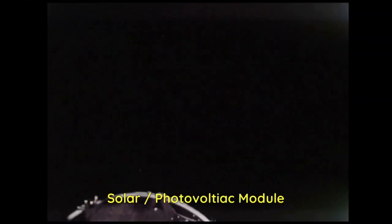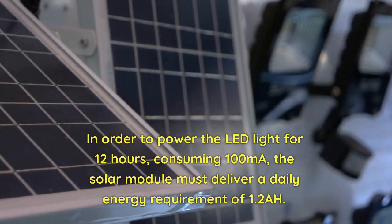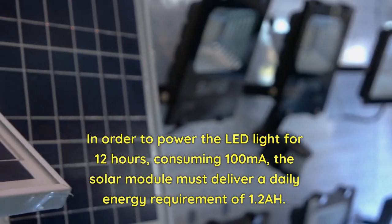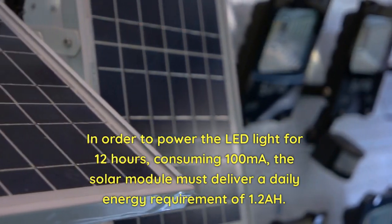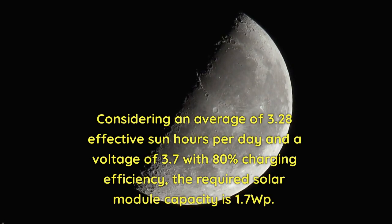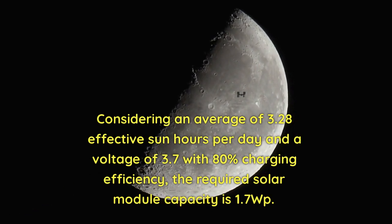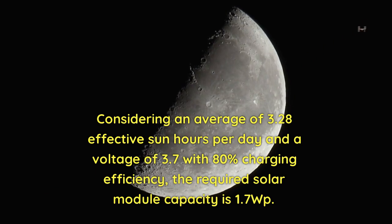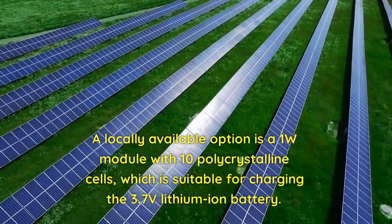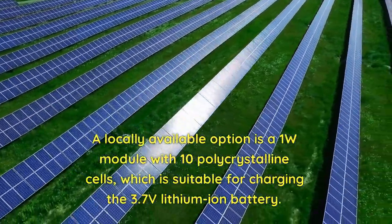Solar photovoltaic module. In order to power the LED light for 12 hours, consuming 100 mA, the solar module must deliver a daily energy requirement of 1.2 Ah. Considering an average of 3.28 effective sun hours per day and a voltage of 3.7 V with 80% charging efficiency, the required solar module capacity is 1.7 Wp. A locally available option is a 1 W module with 10 polycrystalline cells, which is suitable for charging the 3.7 V lithium-ion battery.